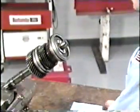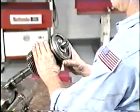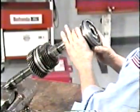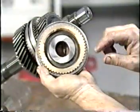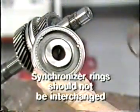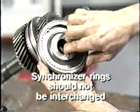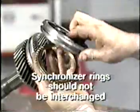Next, remove the third, fourth clutch hub and sleeve assembly, the third synchronizer blocker ring, third gear, and needle bearing as a unit. If the synchronizer assemblies are removed, keep the blocking rings with their original assemblies. Since they've established wear patterns, moving them to a different position could accelerate wear.